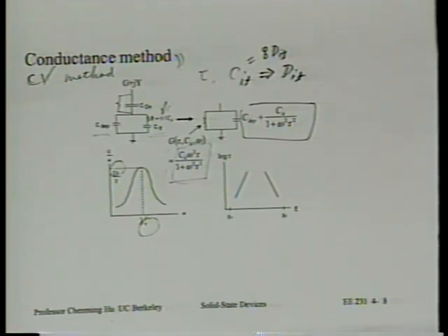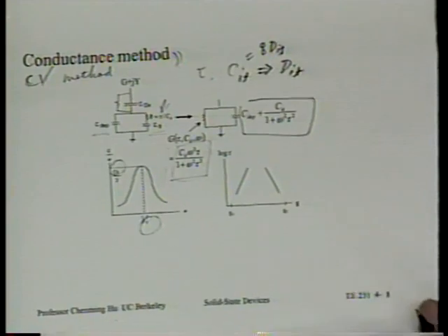Are there other techniques that can do this better? For example, the charge pumping technique perhaps has a relative advantage because that technique is not sensitive to, let's say, the oxide thickness, but if there is a leakage current through the gate dielectric, I suppose actually the charge pumping technique does not have an advantage. As you can see, I'm just thinking through that myself. As I said, this is a new problem that we're running into. That is, how to characterize the interface in very thin dielectrics where the dielectric is quite leaky. You see, all this analysis assumes we have a very good insulating dielectric. That's going to be a problem.